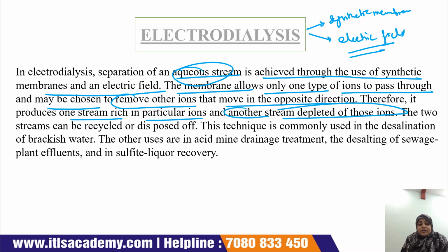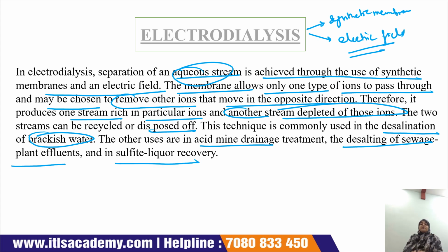So there are two streams that are recycled or disposed of, and this technique is commonly used in desalination of brackish water, and also in acid mine drainage treatment, desalting of sewage plant effluents, and sulfide liquid recovery. So the applications of electrodialysis are in sulfide liquid recovery, desalting of sewage plant effluents, and acid mine drainage treatment. Most commonly we use this method for desalination of brackish water.